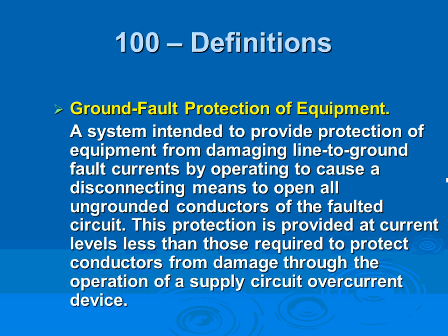Who cares? The smarter than Chad say, wow, at this level, I can have an 800 amp ground fault coming on a system that's 1,000 amps, and the 1,000 amp switchgear is looking there and watching it and thinking it's a load. When in reality it's a ground fault, cooking and burning and arcing and sparking. So long story short, my friend, smarter than Chad decided that if you have a grounded system, you have to have ground fault protection. Otherwise, the ground fault doesn't do a whole lot.